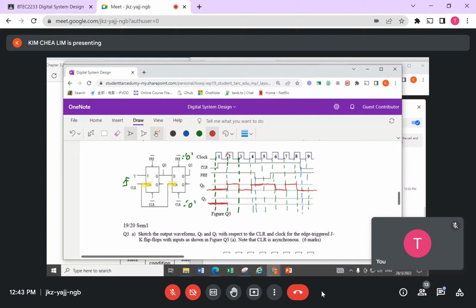They check what the conditions are here. It's a 0. What they are checking is the one weighted in front. Remember the setup time? This one happens, you can say at the same time, but actually with a little bit of delay. So the D flip-flop here doesn't see the input 1 at this instant. What they see, the input there, is a 0, so they are going to output the 0.